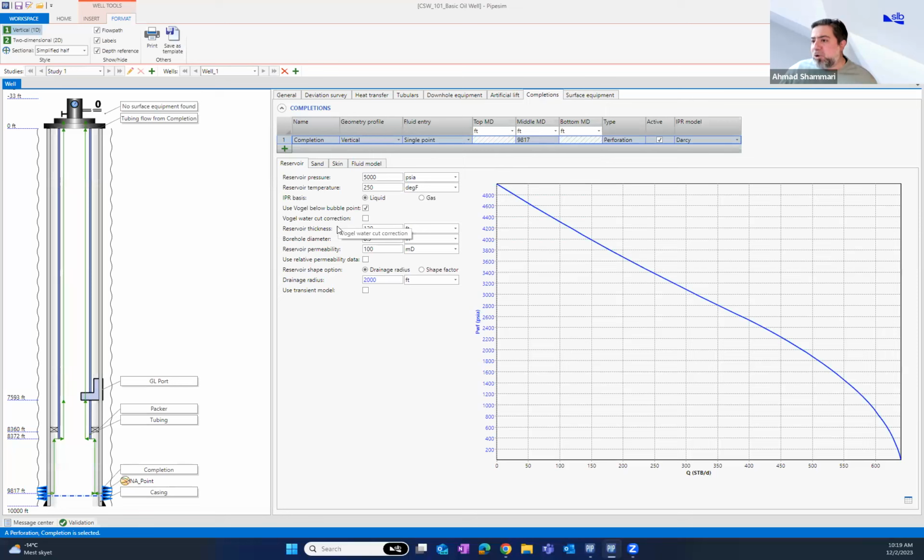model what is called composite IPR, in which if you have water cut, as the water cut increases, of course, there will be less oil. And when you have less oil, the impact of gas on the IPR curve will be reduced, if you know what I mean. So in this case, why do we have a curve after some time?